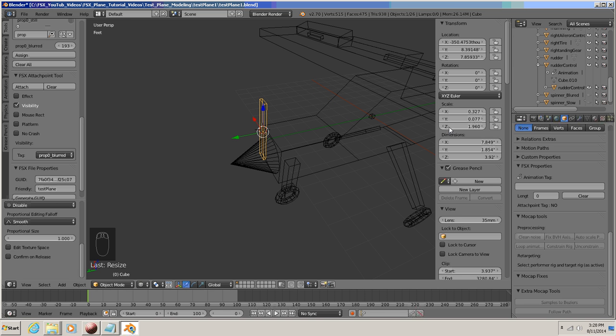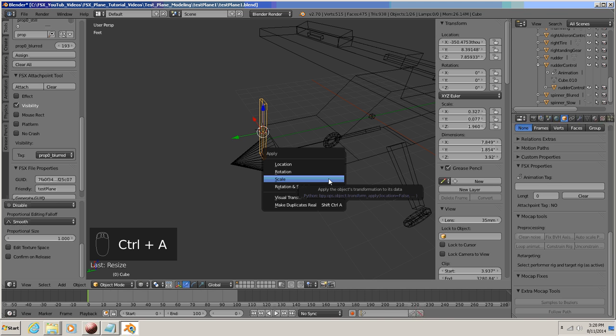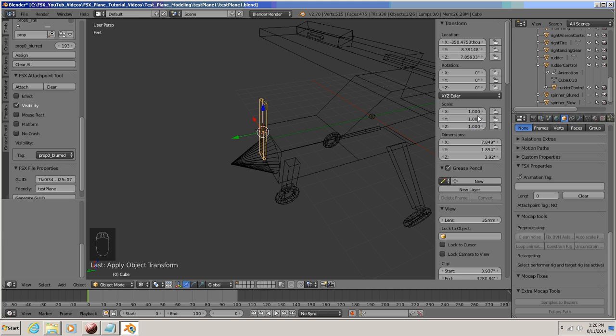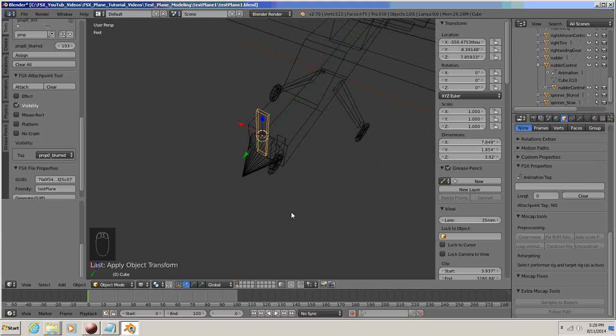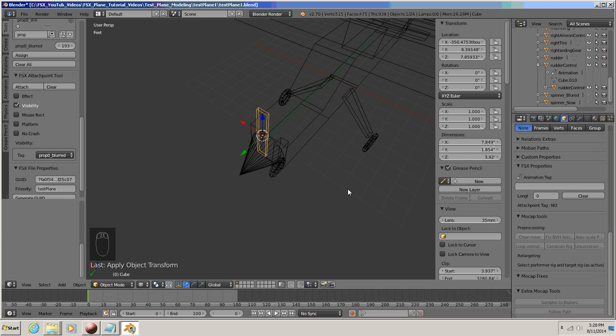So let's go ahead and put it back to default scale. So let's hit Control A. Oops, sorry about that. Hit my microphone accidentally. And hit Scale. Now we're back to default scale. We're going to turn it a little bit. Okay, we're going to now rotate it. I believe in a negative, we're going to put 20-degree pitch on it. So let's rotate in the Z-axis by -20. That's the wrong way. So escape, rotate R in the Z-axis, Z, and 20 degrees. That's good.